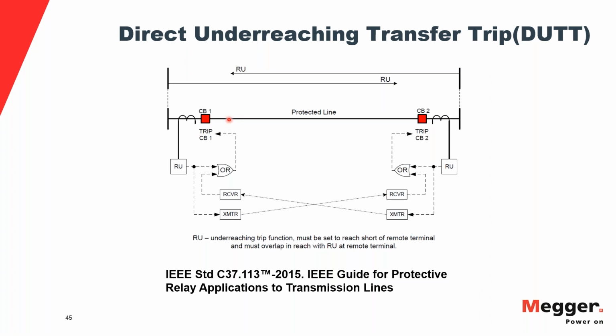What happens here is that, let's say we do not have the scheme. If we do not have the scheme and we have a fault here, which is zone 1 for CB1, and it's zone 2 for CB2, this guy is going to trip instantaneously or with no intentional time delay, maybe under a cycle. But then this guy over here is going to see the fault as a zone 2.